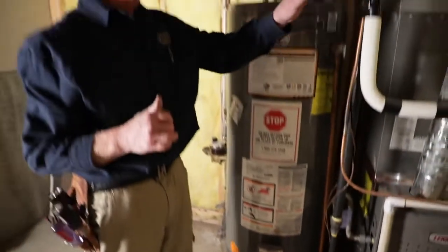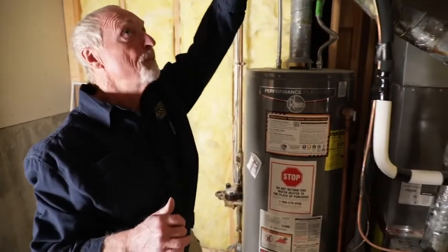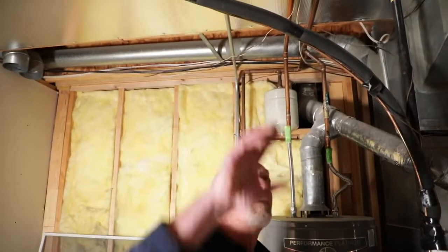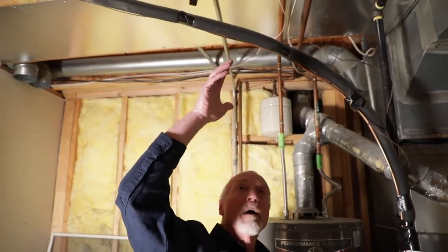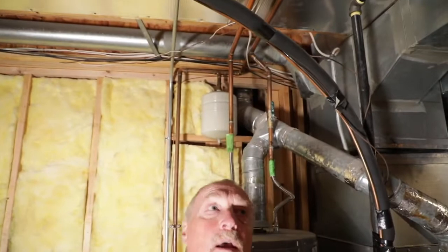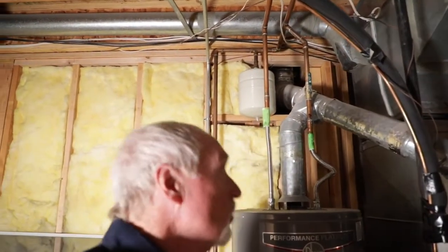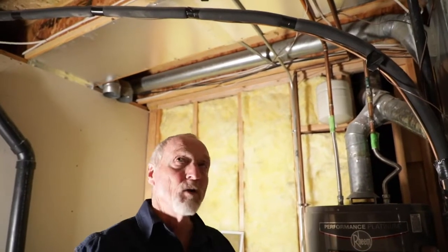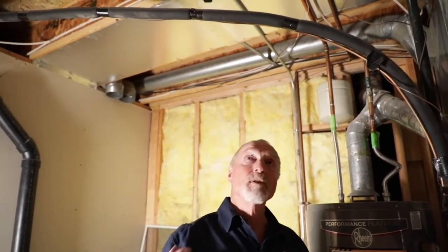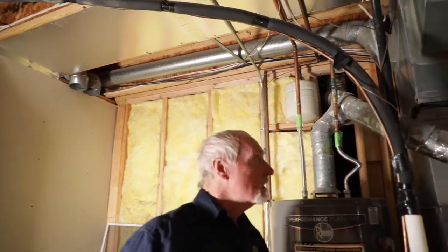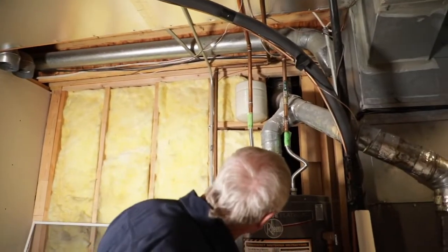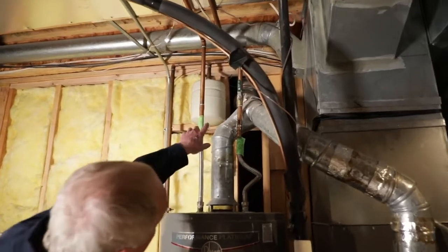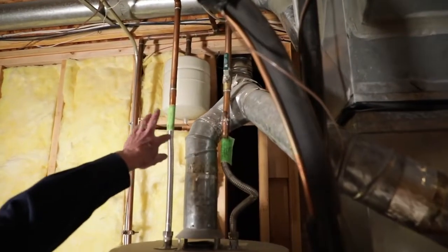So as we walk our eyes up and over our gas line, we're also looking at our copper water plumbing up here. And if you have your gas sniffer with you, you can run that along these connections and see if you get any gas leak. But again, our noses are more sensitive than gas sniffers, and we would probably be smelling it while we're standing here. While we're also here, we're checking our flue, making sure we've got the proper clearances on it going up.